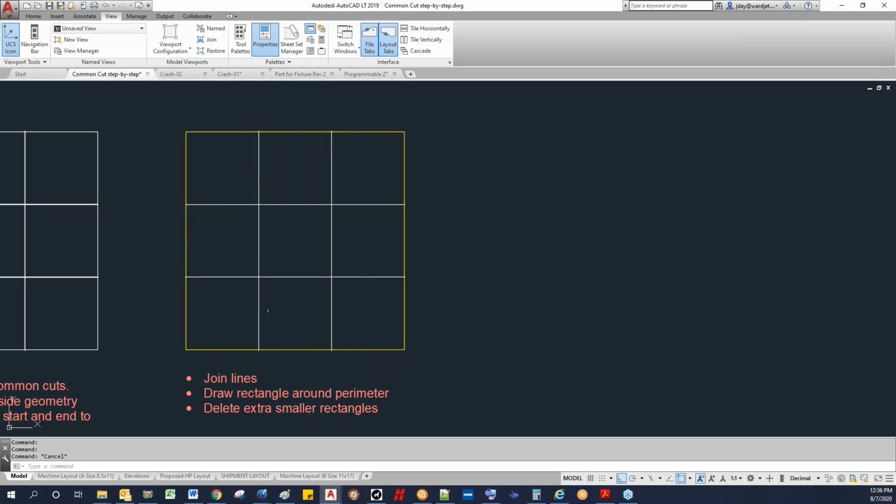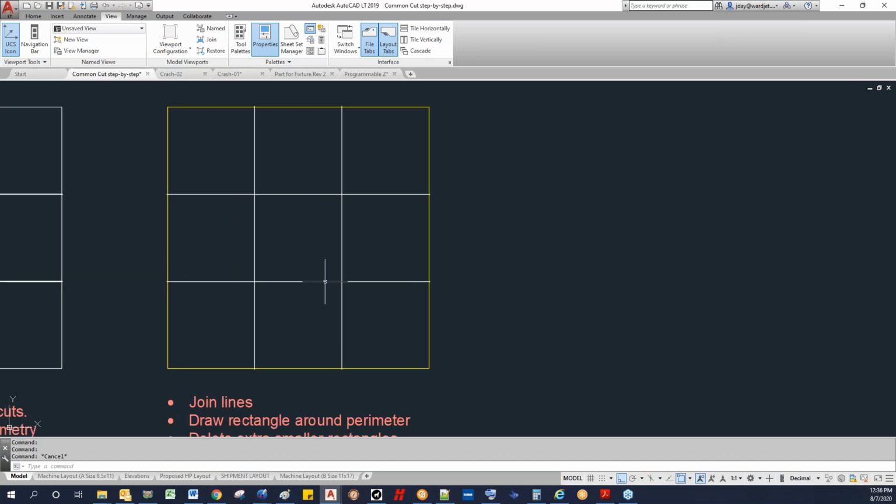And then with that, you'll be able to use the open contour cut command and add your toolpath with that. So that would give you 5 separate cuts, depending on the sequence that you did it at, up, down, across, and then a 5th cut to go around the outside.